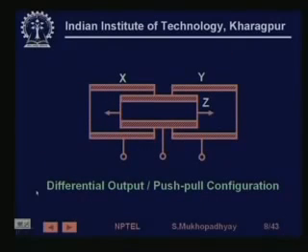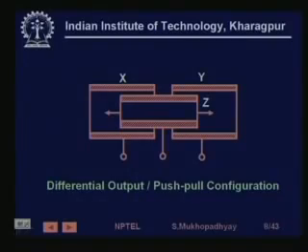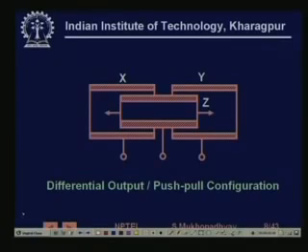This is a case where you have a push-pull configuration. Sometimes we find that push-pull configurations can actually cancel some non-linearities. So not only that, they will also enhance the sensitivity. So here what is being done is that there are two capacitances which are formed. So you know this forms one of the capacitances which is formed between these two terminals, and this is forming another capacitance which is forming between these two terminals.